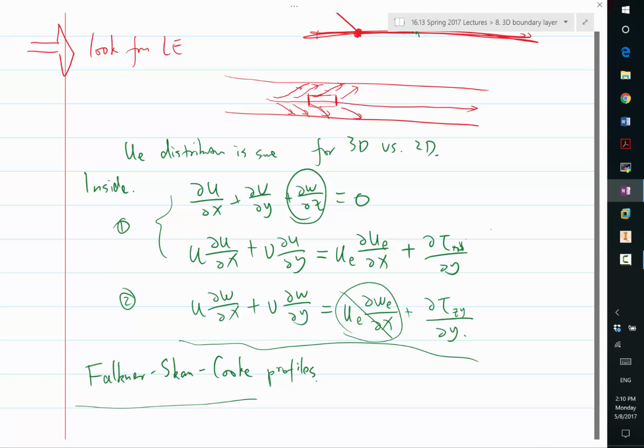But empirically, we find the coupling to be very, very weak, because essentially what this W velocity does to the flow is add a little bit more turbulence, right? And turbulence is actually remarkably insensitive to Reynolds number. I mean, it is sensitive, but you usually have to change the Reynolds number by a large factor, like a factor of 5 or something, to see a significant difference in the turbulent statistics.